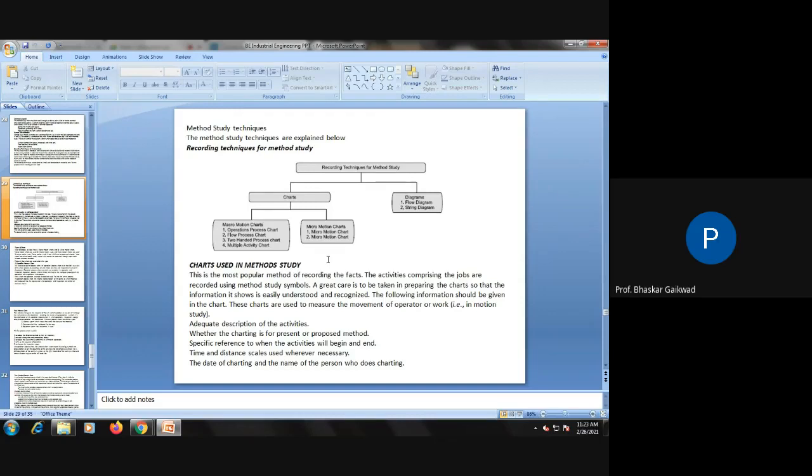What is that operation process chart? It means while doing the operation, what should be the sequence? If a sequence is not right, sometimes more time is required to complete the job. More downtimes will be there, unnecessary movements will be there. So in the operation chart, what types of operation are there and what is the actual time required for them. And by using this, we will calculate the cycle time required to complete the job.